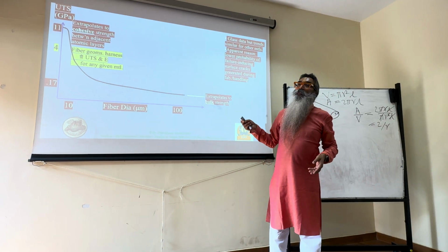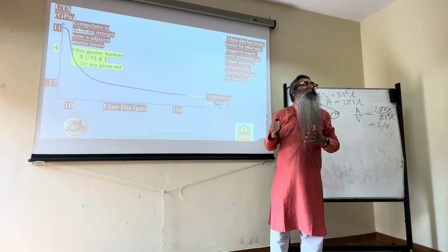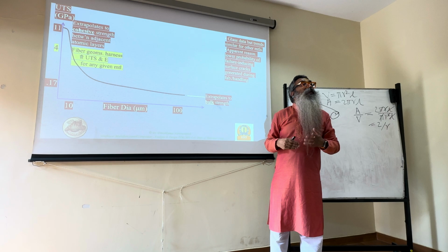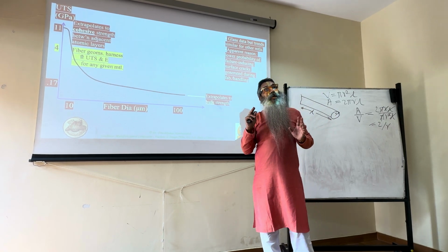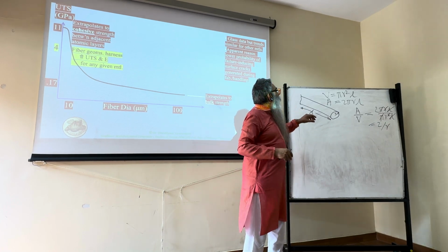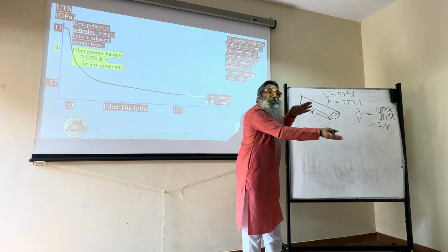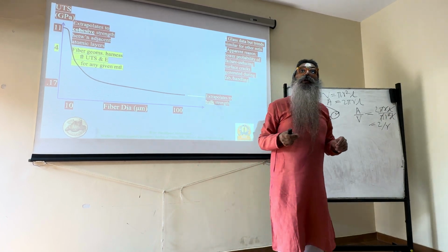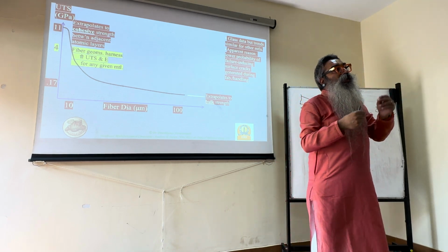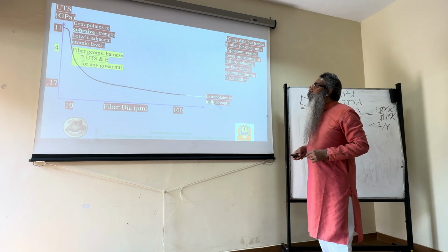Within the parallel of the Newtonian mechanics itself, size effects are there, okay? And they can affect material properties, okay? So we have to be a little careful when we say these two are completely divorced from each other, that is structure's geometry and the structure's material properties. There are certain length scales, especially the smaller length scales, where there can be an interaction between the geometry and the material that you should be aware of, okay?